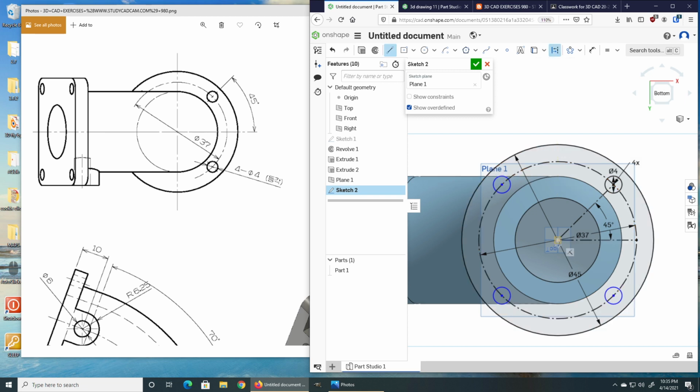If I come in with the line tool, and then dimension that to tell it we're at 45 degrees, that will make it happy. I wonder, does it matter which one I do first? I only had to do 2 of them last time. Can I get away with 1? Nope. Okay, so 3 of them total are dimensioned to 45 degrees. Pretty much everything here is a construction line except for the holes I want in the inner and outer circles. The sketch is done.